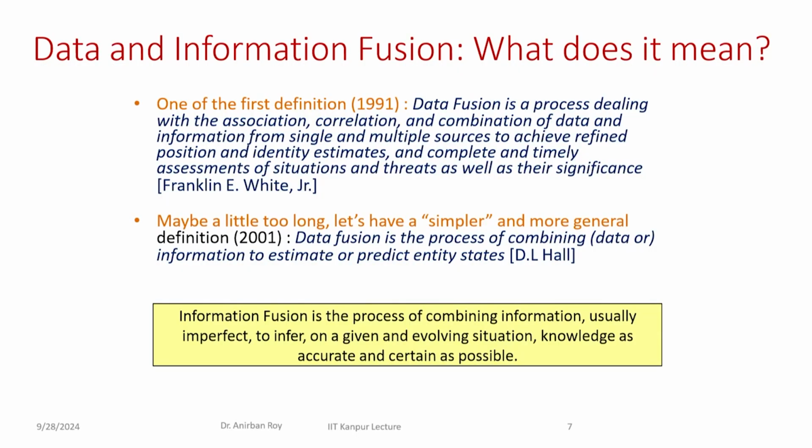Now, what is called association? Association is needed when multiple data are coming and there could be multiple objects. How will you know which measurement corresponds to which target? The radar is not telling you, or your IR or camera is not telling you. How will you do it? So, which measurement is for which target? That part is a statistical correlation, called association and correlation, okay. Or you may not know, the radar is giving me some reflection that could be from no target. So, we need to know that. That process is called association.